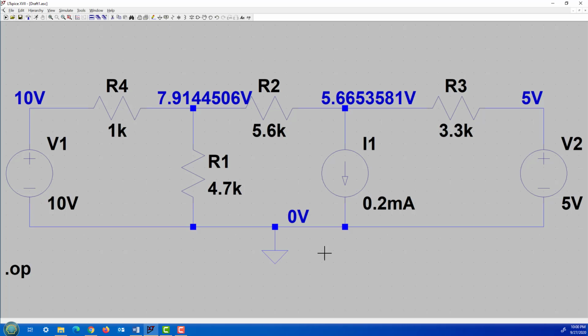But when I ask you for the nodal analysis equations, you'll notice that I only ask you for nodal analysis equations for circuit 2 and circuit 3, which only has resistors and current sources, right? With the voltage sources, it's pretty easy too. I didn't ask you nodal analysis, but with voltage sources, it's easy because if you look at the left node, it's already 10 volts. Look at the right node, it's already 5 volts. So basically, we don't write nodal analysis equations there.